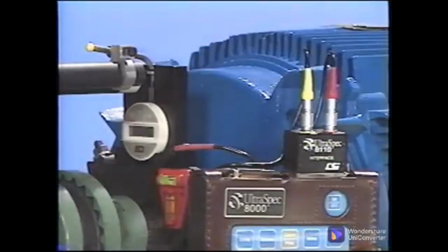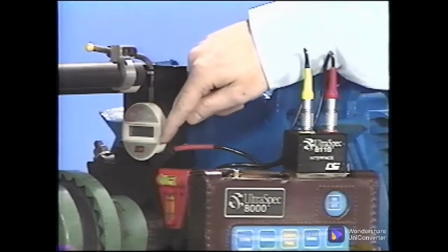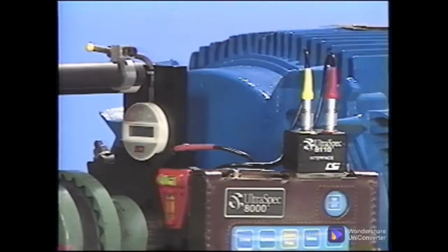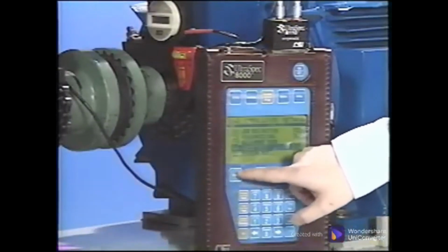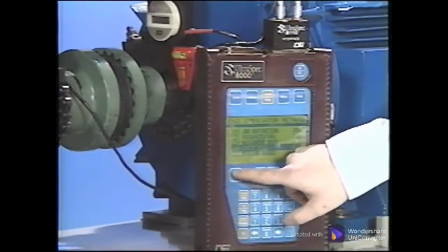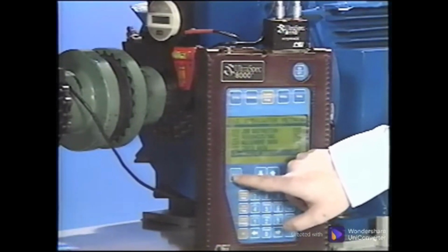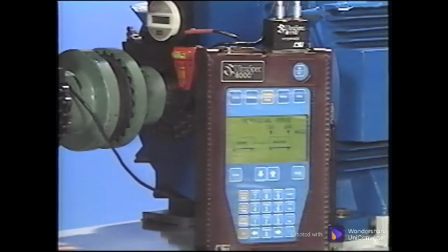The principal difference between the reverse dial indicator method and the electromechanical system is the dials are replaced with digital heads that make the readings and transfer the data into an alignment analyzer, which calculates the machine moves and required shims under each foot. Although the electromechanical system is more costly, the calculated moves reduce time and minimize the error factor, saving manpower and downtime dollars.